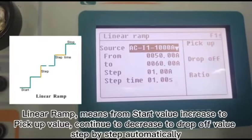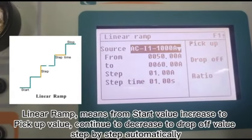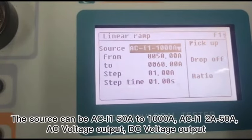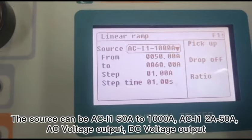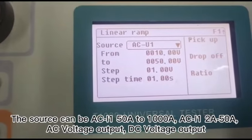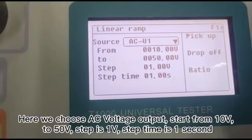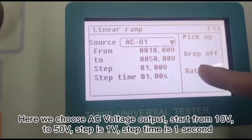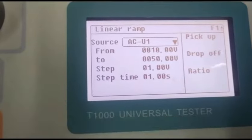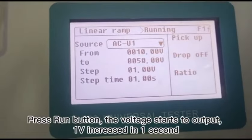Linear ramp means from start value increase to pickup value, continue to decrease to drop off value step by step automatically. The source can be ACI1 current output from 50 amperes to 1000 amperes, ACI1 current output from 2 amperes to 50 amperes, AC voltage output, DC voltage output. Here we choose AC voltage output, start from 10 volts to 50 volts, step is 1 volt, step time is 1 second. Press run button, the voltage starts to output, 1 volt increased in 1 second.